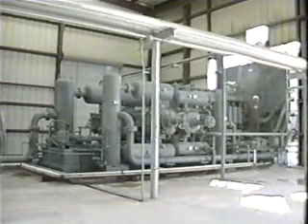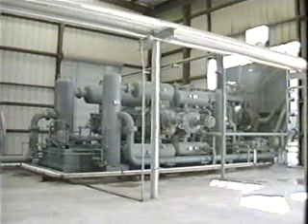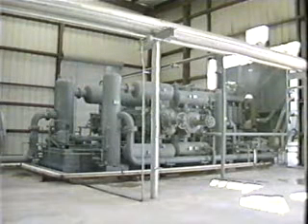On the electrical system, look for damaged wires on the ignition unit, coils, and spark plugs. Be sure all connections are tight and report equipment which needs replacement.